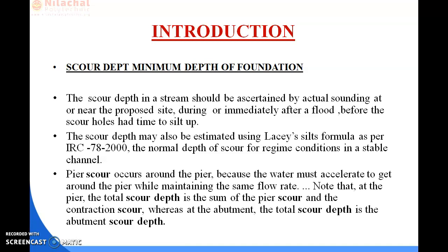The scour depth in a stream should be ascertained by actual sounding at or near the proposed site and during or immediately after a flood, before the scour holes have had time to silt off. Okay.